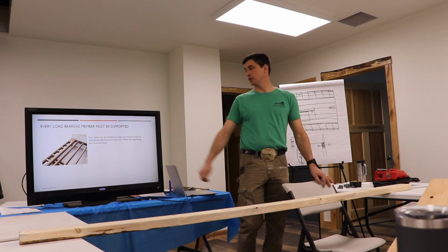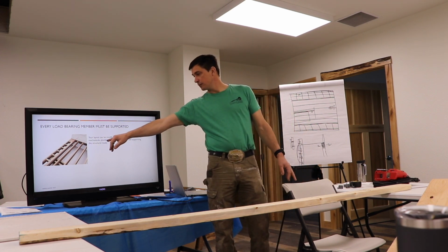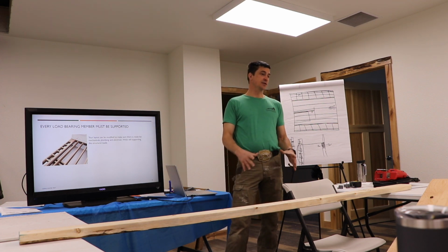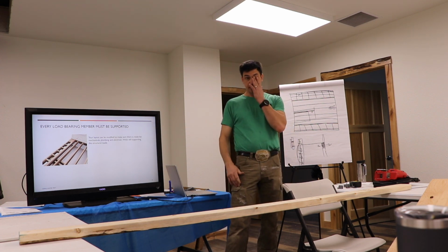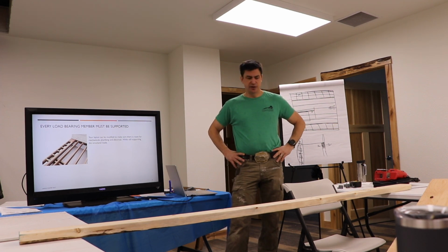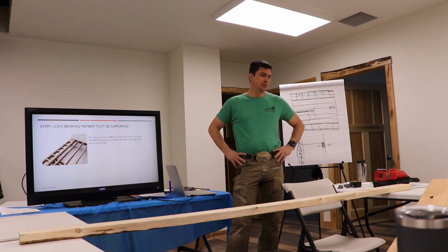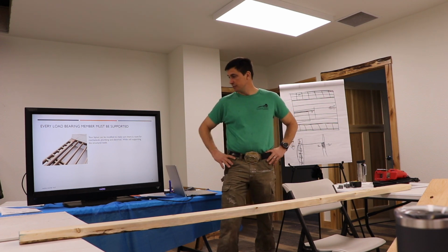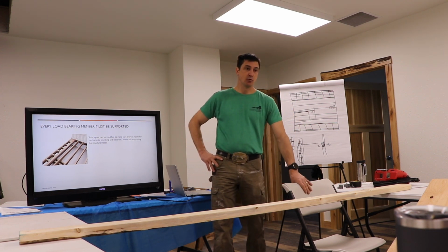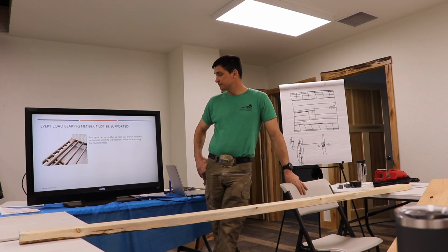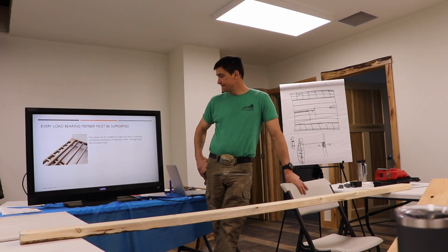Or if you're modifying for plumbing, like a toilet flange or a bathtub drain, that's the other one to look for. Tub drains are not as difficult because it's just a 2-inch pipe, so it's a lot easier to adjust around the floor joists. How big is the toilet pipe? 4 inches.